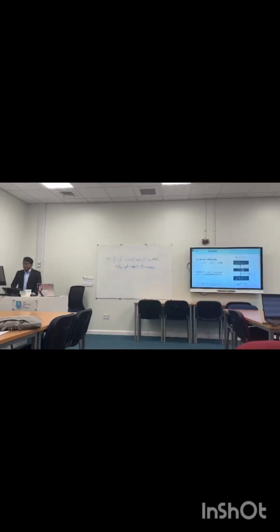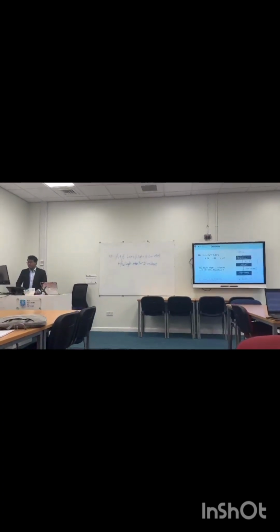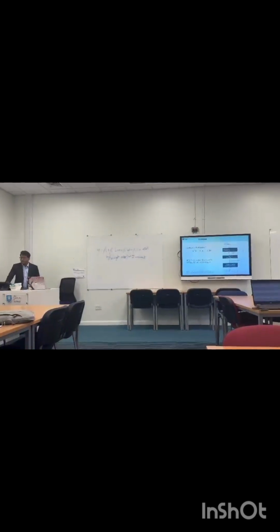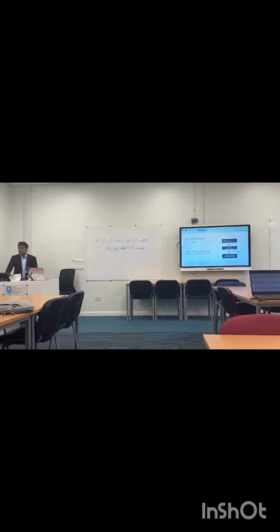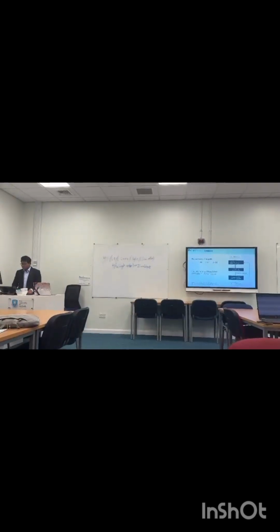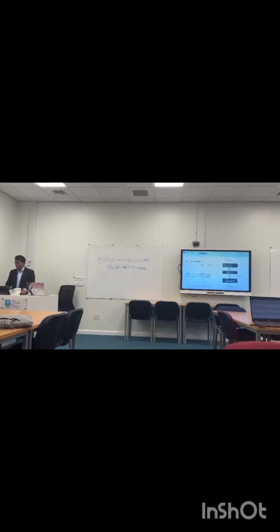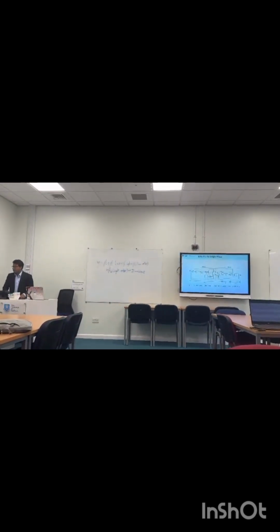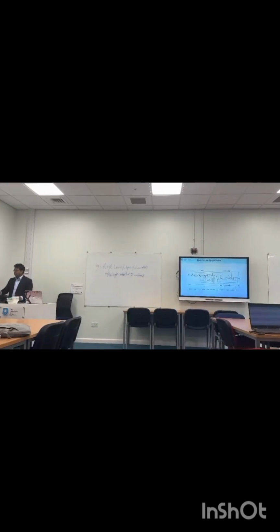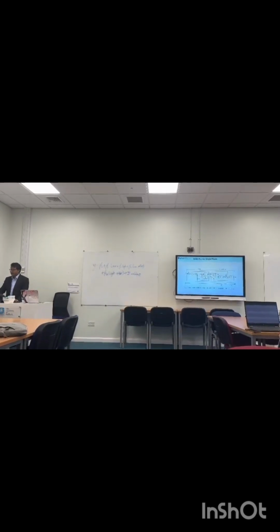SOGI PLL is a second order generalized integrator phase locked loop, mainly used for single phase systems, and synchronous reference frame is mainly used for the three phase reference frame. And this is the flow chart. I already mentioned it in previous slides. And this is the common SOGI PLL diagram.